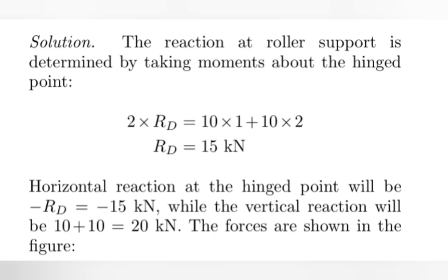So the thing is, a force of the same magnitude but opposite direction should act at point A, to balance that horizontal reaction and be in equilibrium, right? So the reaction force at point A would be minus 50 kilonewton. Basically, one is compression and one is tension, you don't take that into consideration.